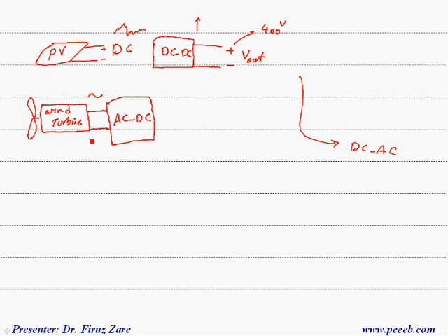That means if the frequency and voltage fluctuate, here we get DC voltage, and the voltage across this output is not regulated. So another possibility is we can use a DC to DC converter again. That means we can regulate this voltage, and here we can get the same voltage level. We can design this converter in such a case to get 400 volts.